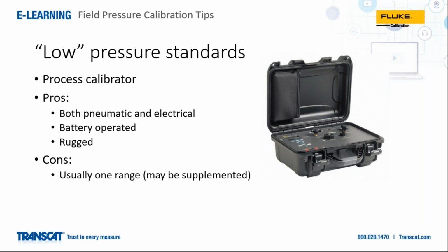All right, let's go on to the next one. What is the right fluid to use for hydraulic calibrations? It's a good question. It's tough because the right fluid is going to be dependent on the application. As I touched on earlier, you have issues with compatibility. So some people choose to pick a default that works in many cases. They may pick distilled water, for instance, because it's relatively benign to most environments. They may choose to mix it with something like denatured alcohol to prevent biological growth. If the standard is sitting around for a while, you don't want to open it up and have it full of algae.